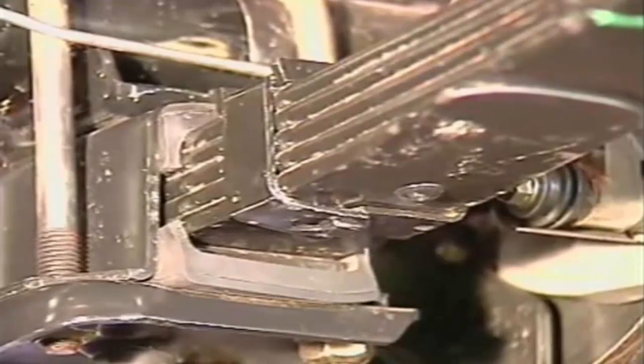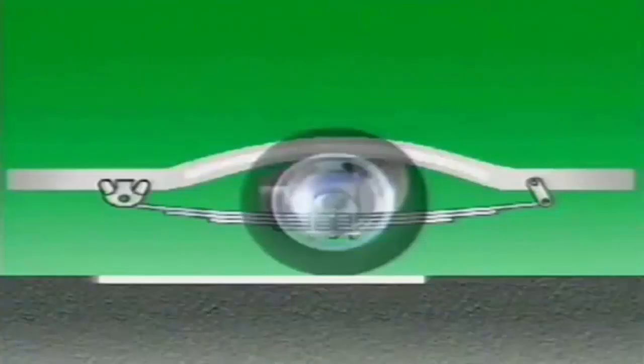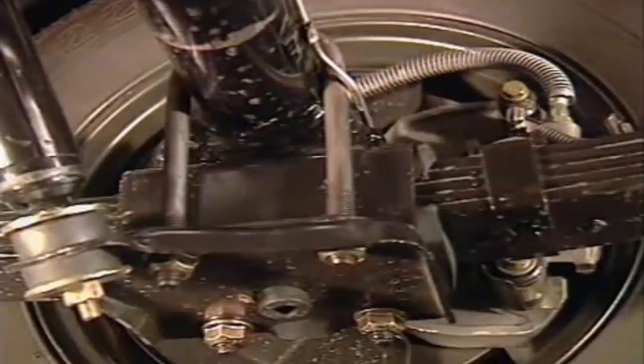Leaf springs consist of one or more flat springs made of tempered steel. A number of leaves of different length are used to form a multi-leaf spring. They are held together by a center bolt that passes through a hole in the center of each leaf. It is also used to locate the axle on the spring. The axle is then clamped to the spring by U-bolts that wrap around the axle housing and through a spring plate underneath the spring.